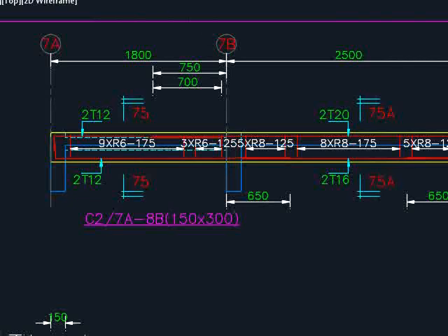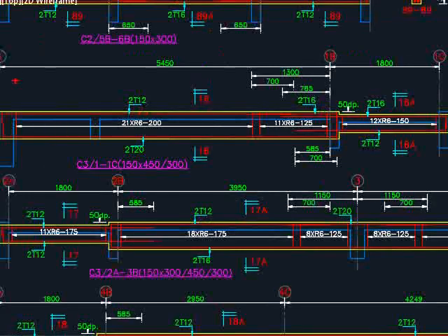As for the lapping of the reinforcement bar, normally we do it near the support, because it is beneficial at the regions of high shear, and the tension resistance of the reinforcement bar may be questionable at the high moment region. To avoid that, normally we'll put the lapping near to the support and not at the midspan of the member. Maybe we look at another example here.